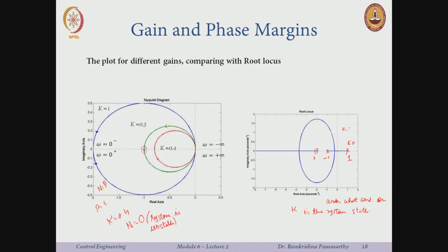Let us then do something else. Say I have a system with a pole at minus 1, a pole at minus 2, a pole at minus 3, and there are no zeros, and I will just do all the rules of the root locus. So, one branch will go to infinity this way, and these two will meet here, and they go this way.